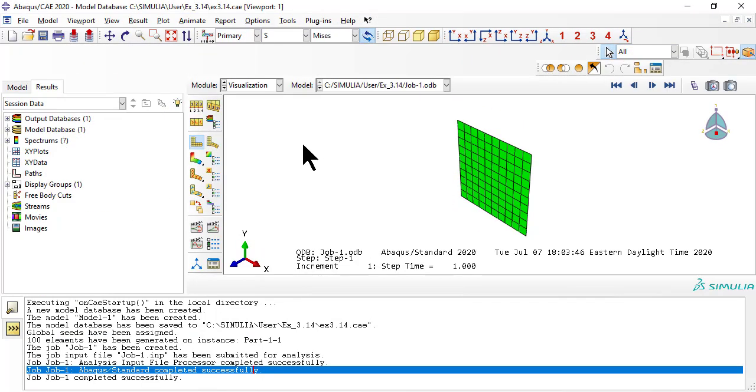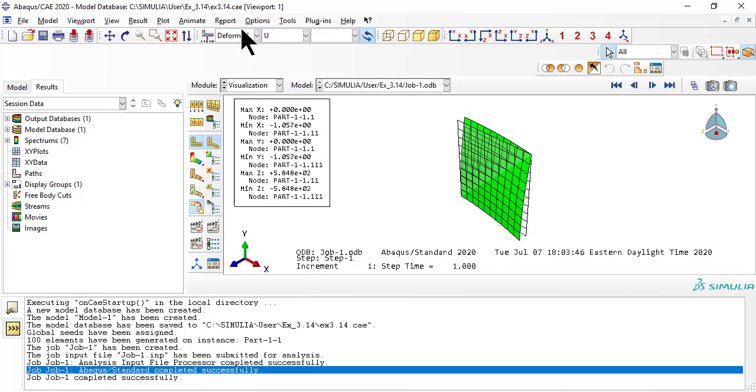Since the laminate is a 0/90, not symmetric with respect to the middle surface, when the temperature changes, one lamina shrinks more than the other, and the plate deforms to the shape of a horse saddle.